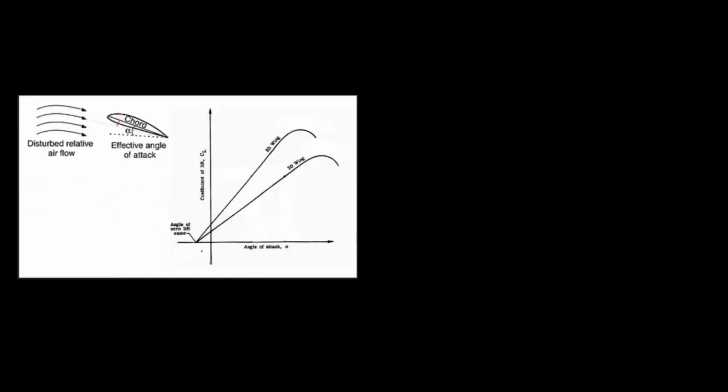Yeah, we discussed how the CL varies for aerofoil and wing. If you take the wing, there will be a downwash, and this is how the velocity varies. So from here only the side leakage flow and the vortices are starting. So from here onwards, the velocity is increasing, but this effect is there in the front region also. So this downwash reduces the flow deflection and angle of attack. So CL is decreasing.